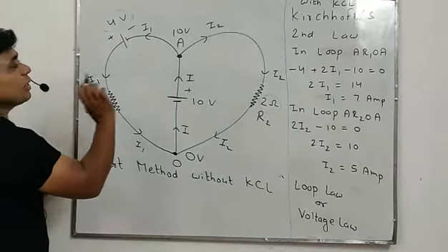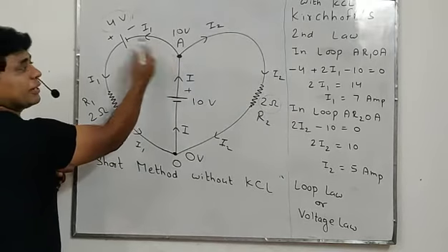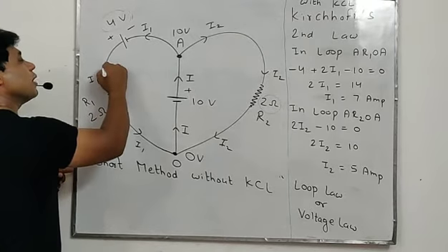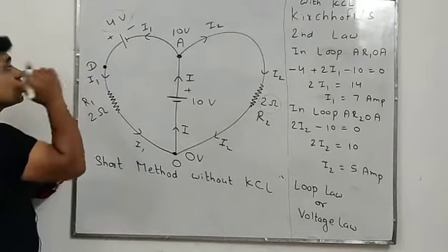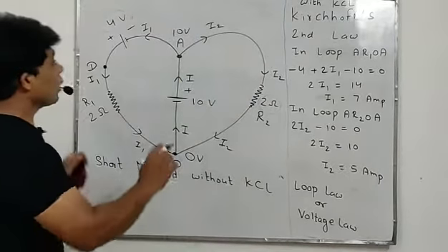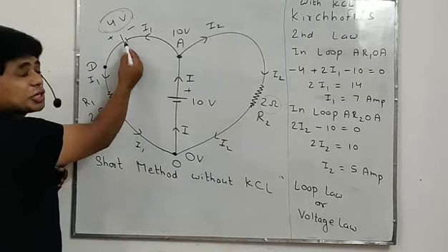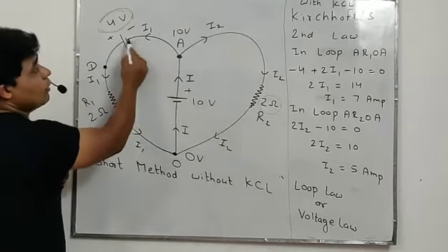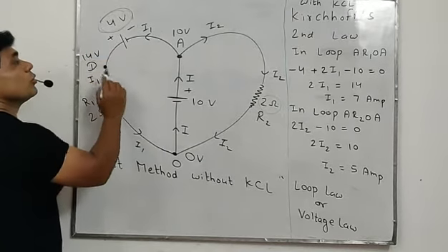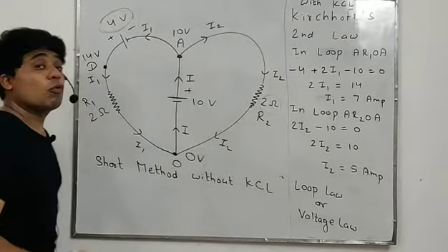Okay. Similarly, this is 10 volt. And when we turn to that side, this is a 4 volt battery. Let this other point be point D. According to this, what should be the potential at D point? We require 4 volt, since we are given a 4 volt battery. If the negative is at 10 volt, then the positive will be, suppose, 14 volt. So positive minus negative, 14 minus 10, gives 4 volt.